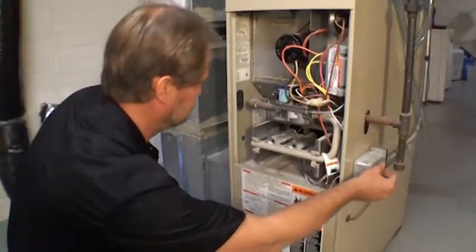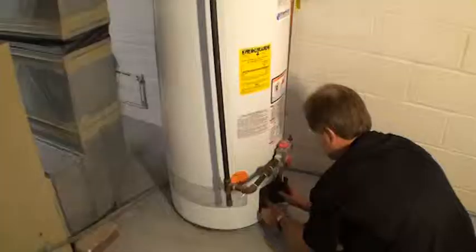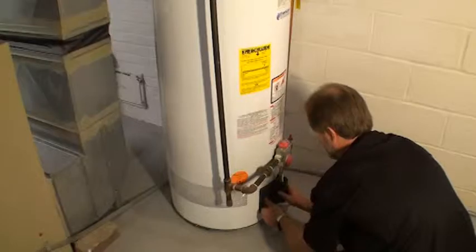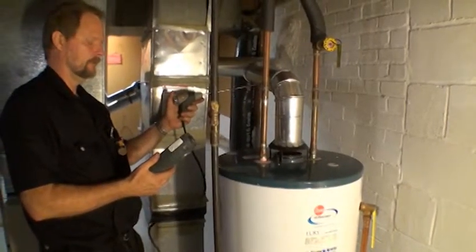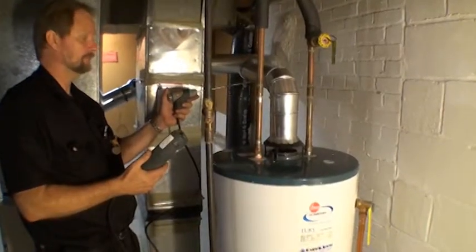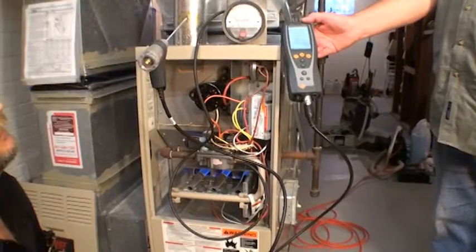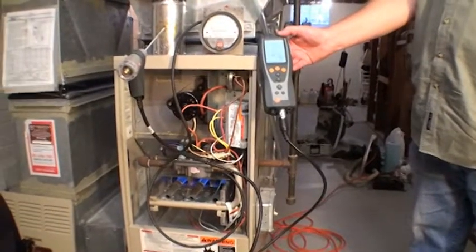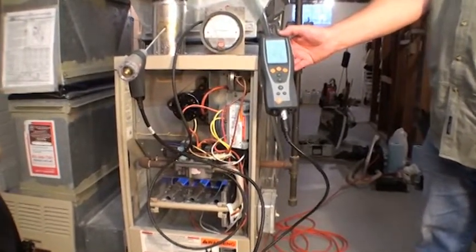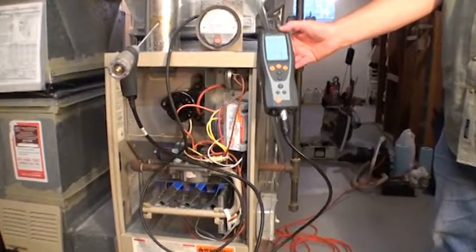Turn on all combustion appliances such as furnaces, boilers, space heaters, and water heaters. Allow these appliances to operate for 5 minutes and then take their draft readings. In dwellings with forced air systems, make sure the furnace fan is on and running. If a plus 90% high-efficiency sealed combustion 2-pipe furnace is present, it is excluded from the worst-case draft test, but must be operating when the other appliances are being tested.